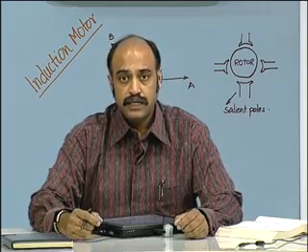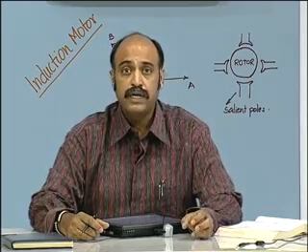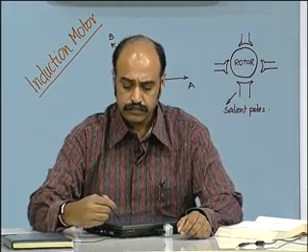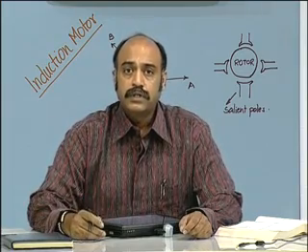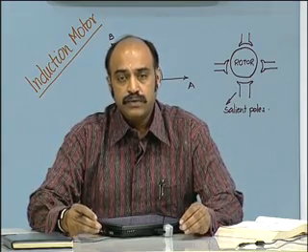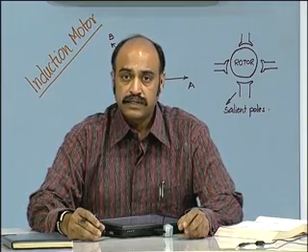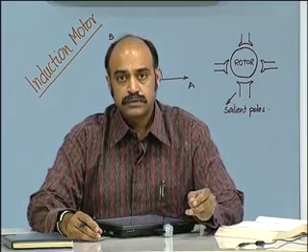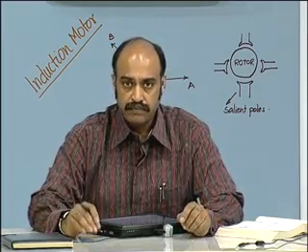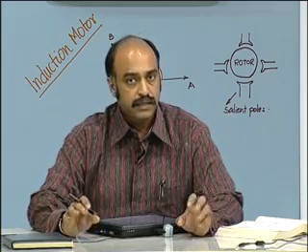But the important concept now is that how do we bring about a relative motion between the field in the motor and the rotor conductors. Now, to achieve that, we use the three-phase source. So, in the three-phase source, we have three sources wherein they have the same effective amplitudes, however, they are 120 degrees apart in time.